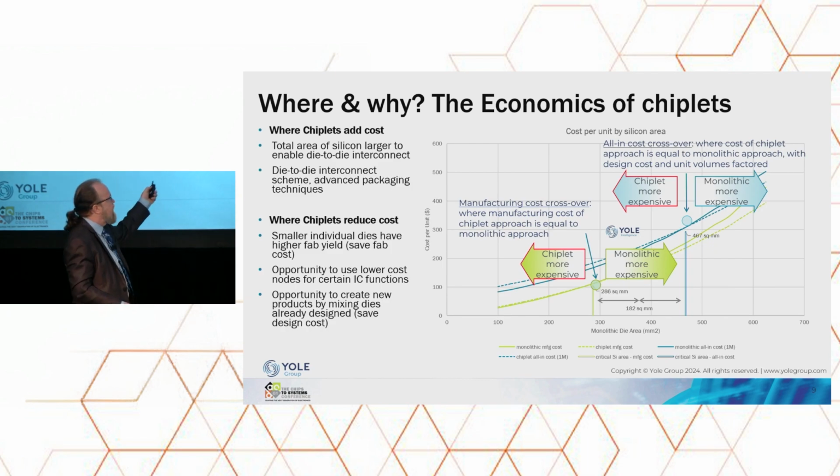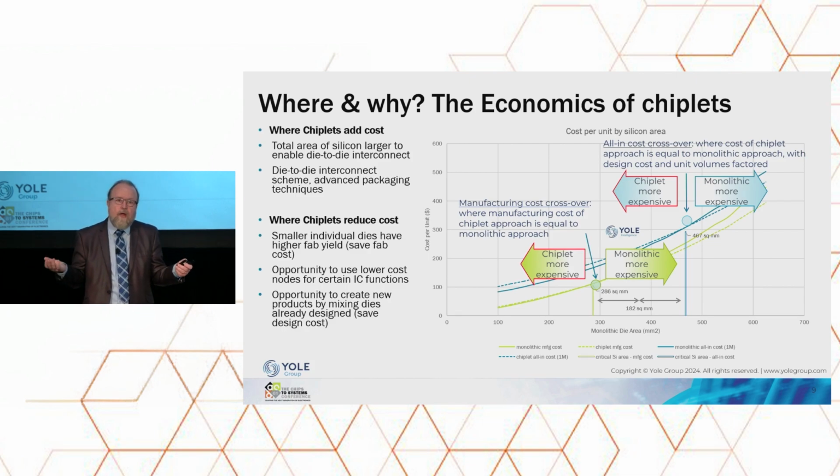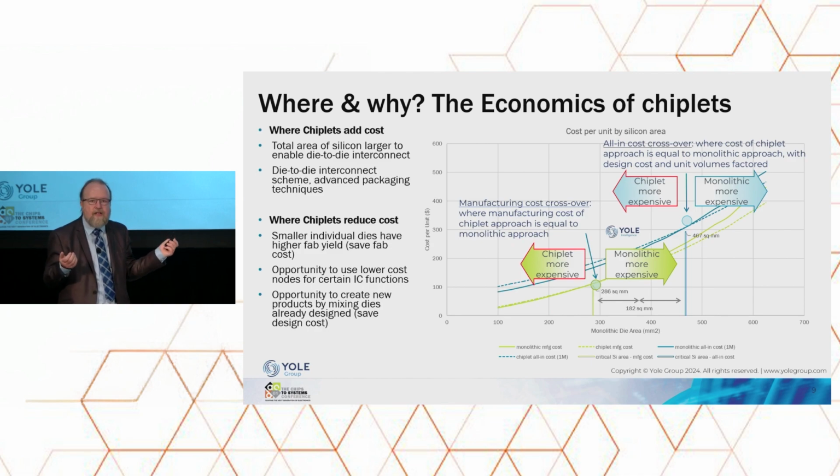And so we did a second analysis to incorporate design costs, and we find that somewhere in between 400 and 500 nanometers square, we still see chiplets going to be the optimal solution in terms of total cost of design. And then ultimately down the graph, this graph doesn't take into account that there's still the physical barrier of when the large heterogeneous die becomes too big for a reticle. Now you're talking about equipment replacement for manufacturing, which is just not going to happen. Okay.